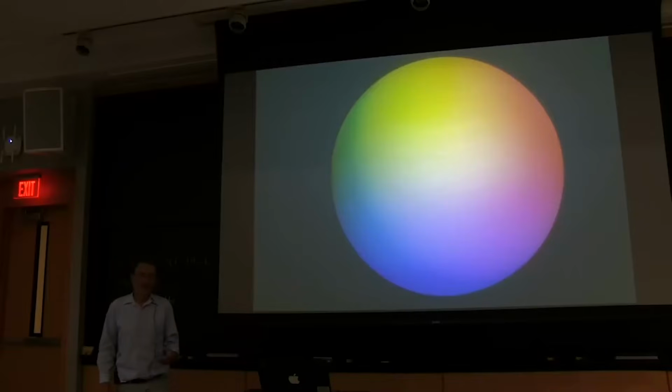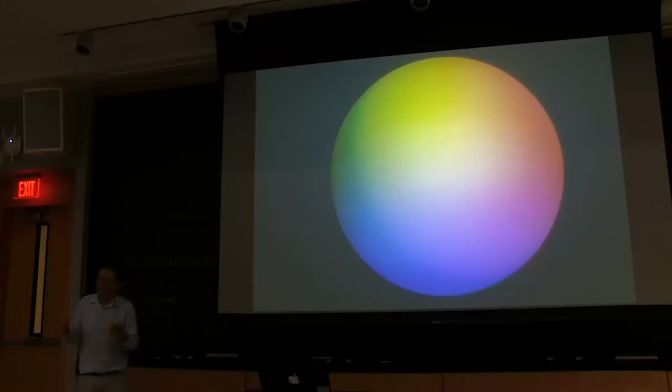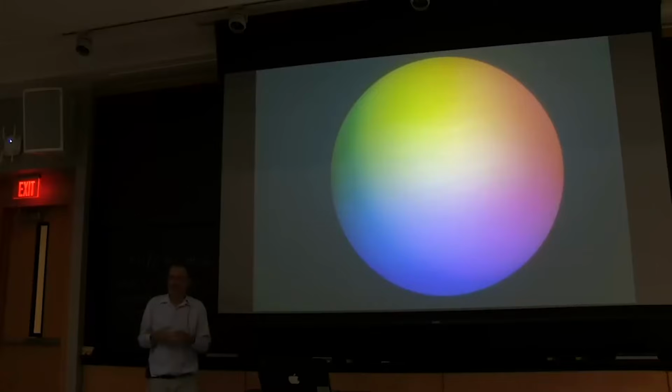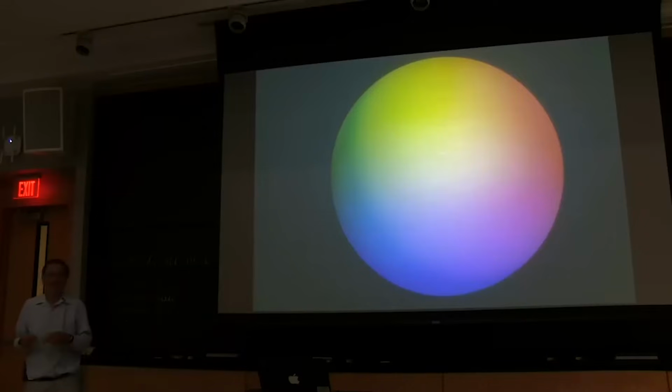Another way to look at it is that a pixel is small. How big is a pixel in a typical camera? So we can sort of figure it out. The chip is a few millimeters by a few millimeters, and we've got a few thousand columns and rows. So it's sort of a few microns, and there are huge trade-offs. Like the one in your phone has smaller pixels. The one in a DSLR has larger pixels. But in any case, they're tiny.